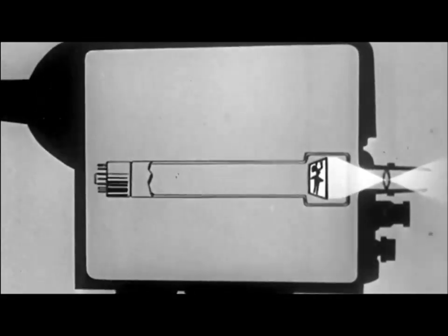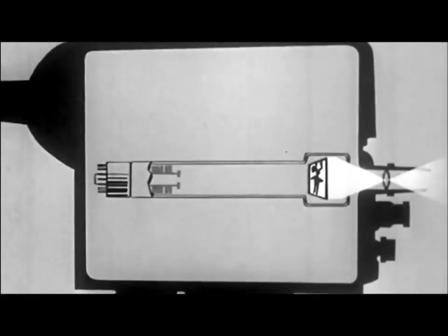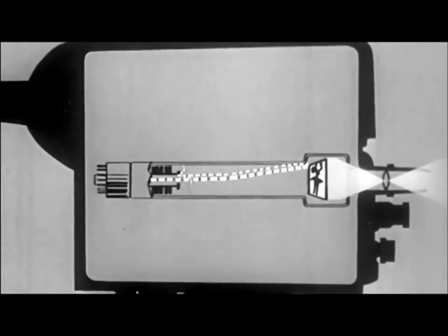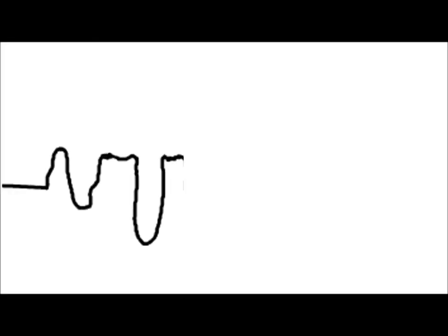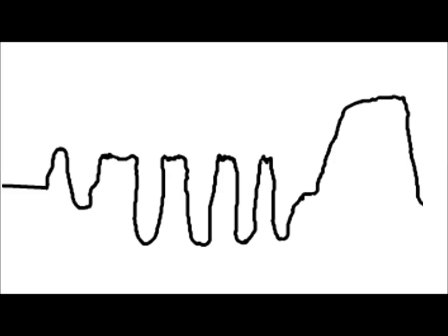To understand how that worked, let's start with the camera. Back in the 1940s, the television camera made pictures using a camera tube. The live scene was focused through a lens onto the face of a photosensitive plate at the front of the tube. That surface was scanned with a stream of electrons, which turned the original brightness and darkness of the scene into a constantly fluctuating voltage.